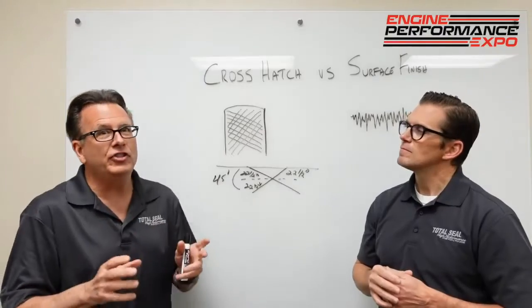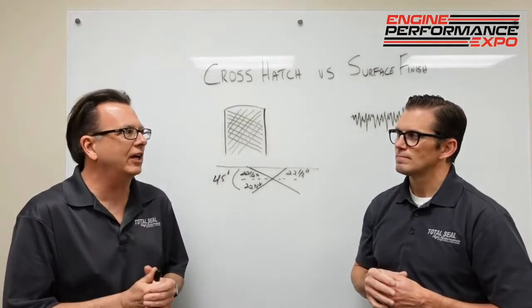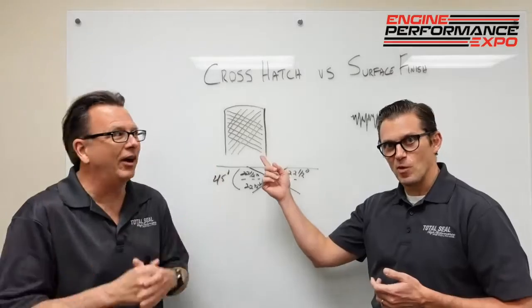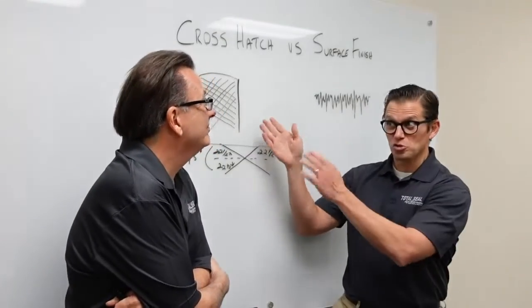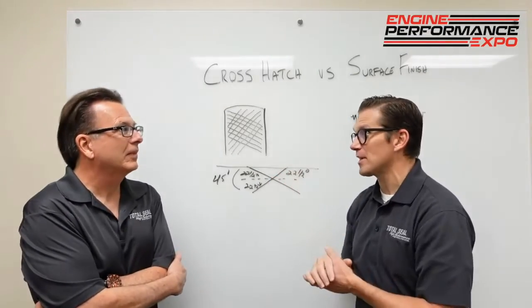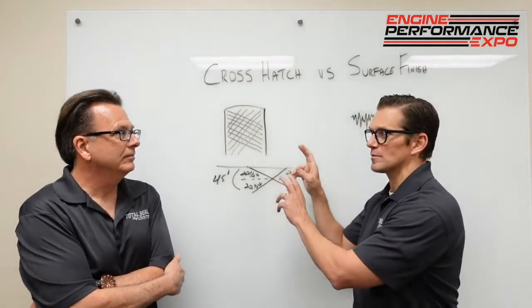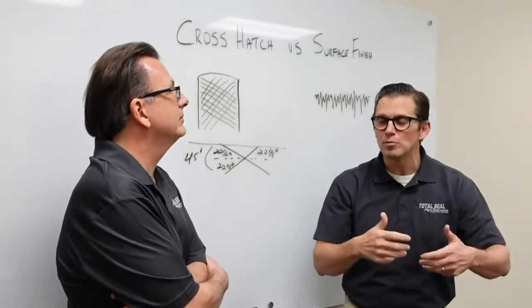So even though you've set it the way the manufacturer or the machine said to do it, you still want to check that angle, because even though you did it right, it may have done it wrong. Well, that's a great point. That's why it's important to trust but verify. So you need to be able to measure that, because it is a very important consideration.